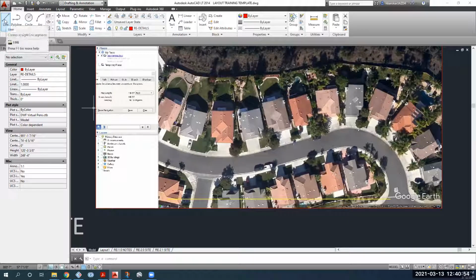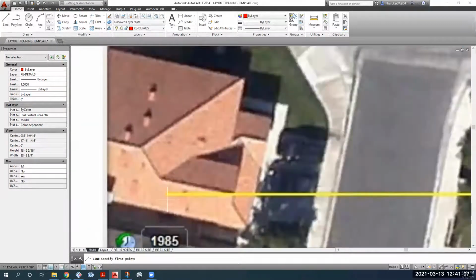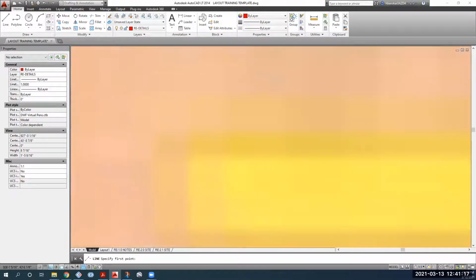So to do that, here on the top left corner, there is this line segment. In AutoCAD, you can work in this mode called ortho mode. In ortho mode, everything will be in 90 degrees, so the cursor will only move at 90 degrees: either east or west, or directly north or south. So what I do is I zoom in all the way, and you see where the pixel for this line actually starts.